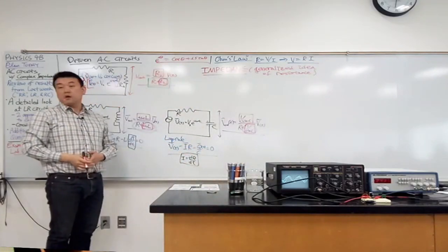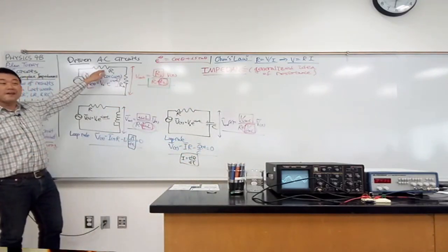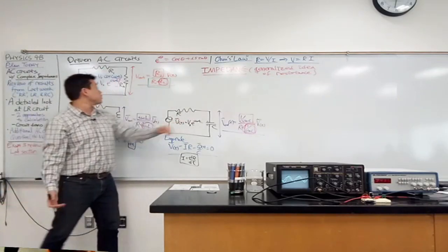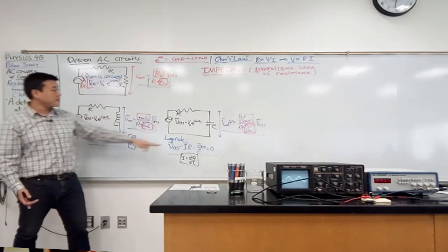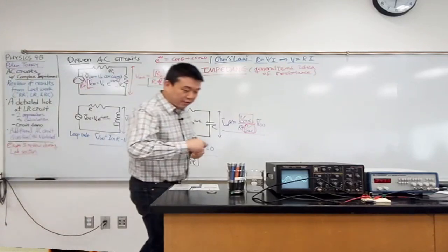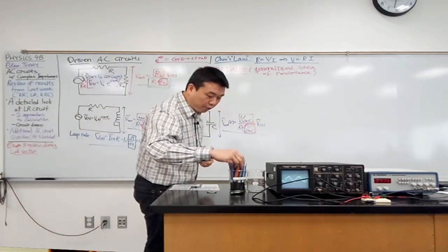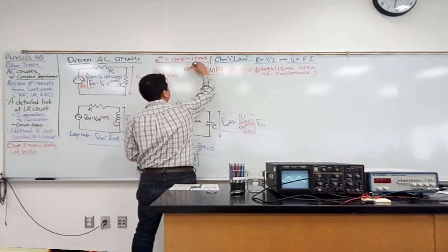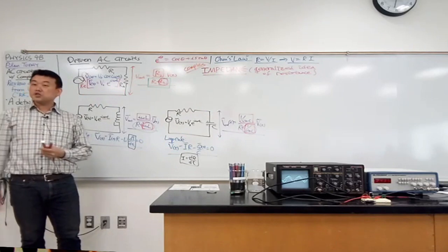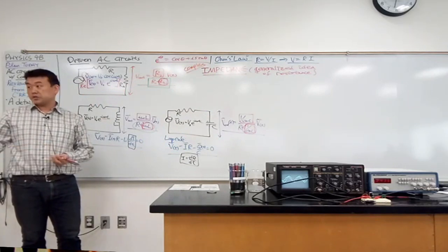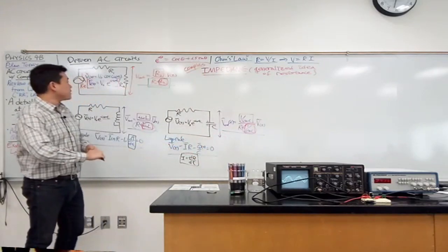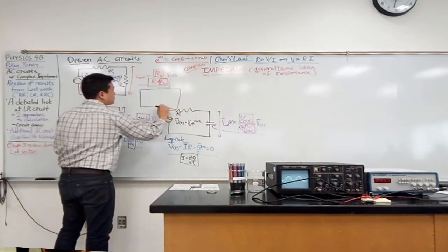Whereas resistance will apply only to, well, resistors, impedance can be used to describe properties, characteristics of resistors, inductors, and capacitors. And the way I teach this section of the class, I am always going to call this complex impedance, because impedance is a complex number. In your textbook, they will try to cover this with phasors. So in a phasor diagram, this is a diagram that you might find in your textbook.